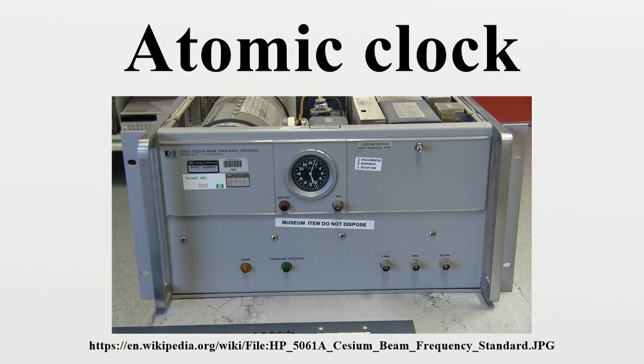The actual time reference of an atomic clock consists of an electronic oscillator operating at microwave frequency. The oscillator is arranged so that its frequency-determining components include an element that can be controlled by a feedback signal. The feedback signal keeps the oscillator tuned in resonance with the frequency of the electronic transition of cesium or rubidium. The core of the atomic clock is a tunable microwave cavity containing a gas. In a hydrogen maser clock, the gas emits microwaves on a hyperfine transition. The field in the cavity oscillates, and the cavity is tuned for maximum microwave amplitude.